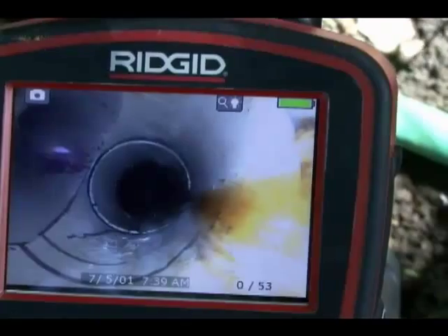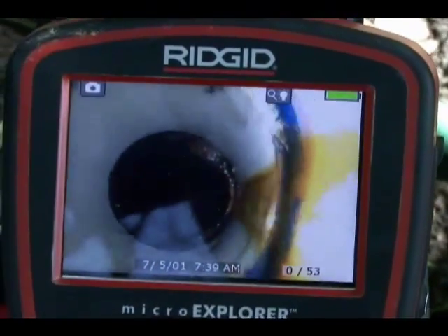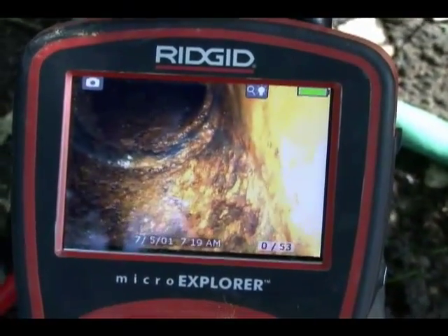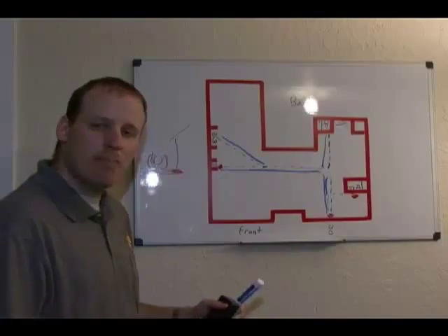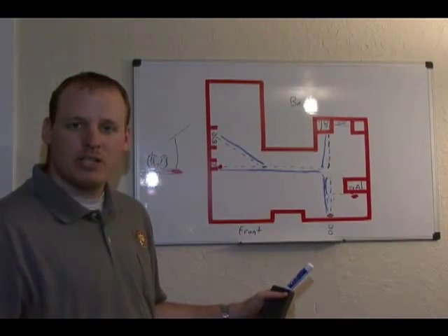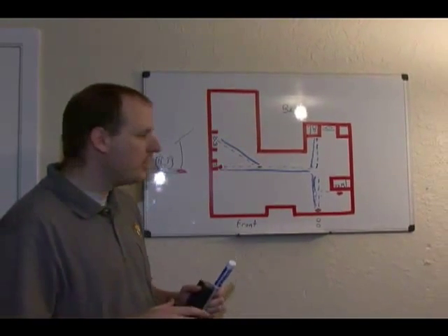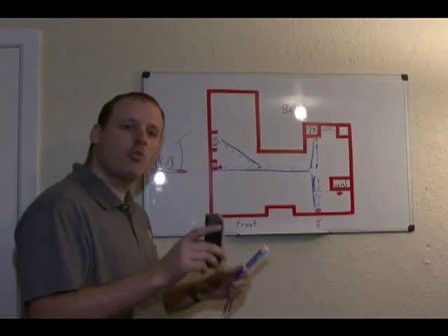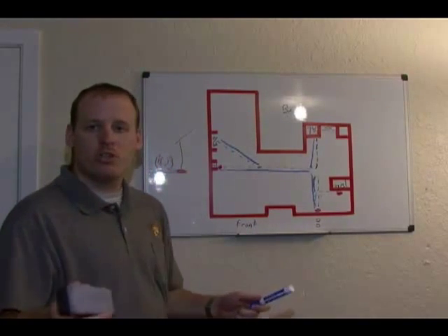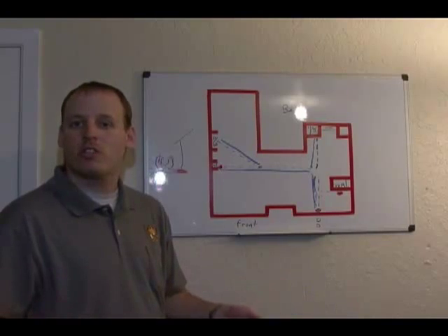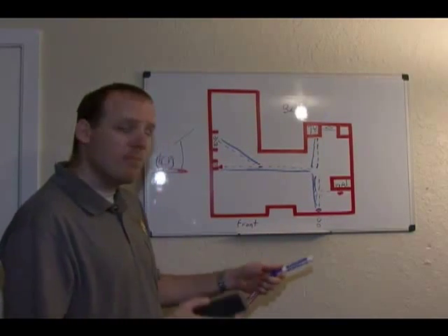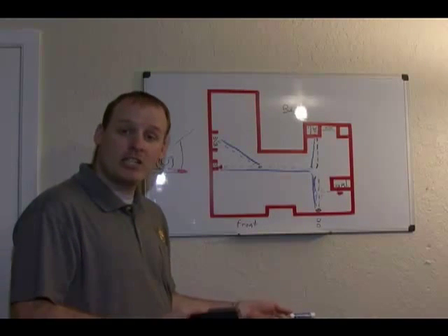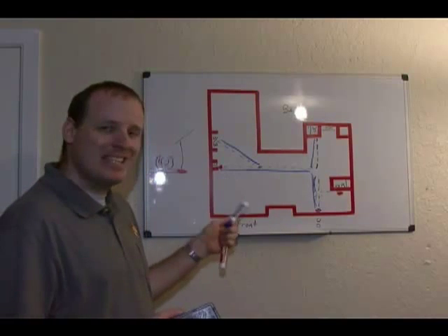Using a sewer camera as a primary leak location tool is very improper. It is not the right way to do leak detection. A lot of companies in Dallas only use a camera to locate leaks. They send the camera in different spots and look for things that don't look good. They'll tell you they're looking for leaks, but really they're looking for something that doesn't look right. What may look like a leak most likely is not a leak, and vice versa.